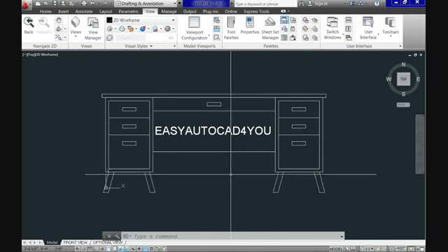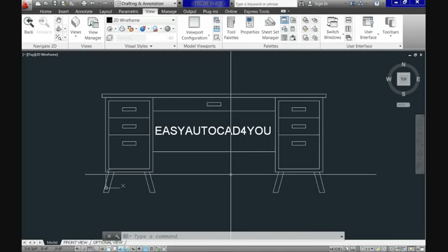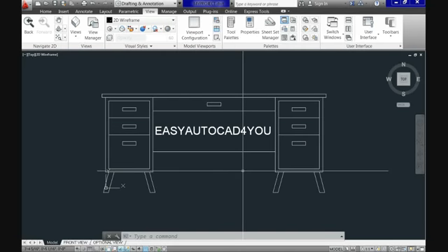By this, I mean that for now, you could specify an architectural template, and you might want to save it as architectural DWT for you. But then you might keep adding things that you will do only once. Now try it on your own, and don't worry if you do something wrong. You can always undo any mistake by going to the undo button on top.